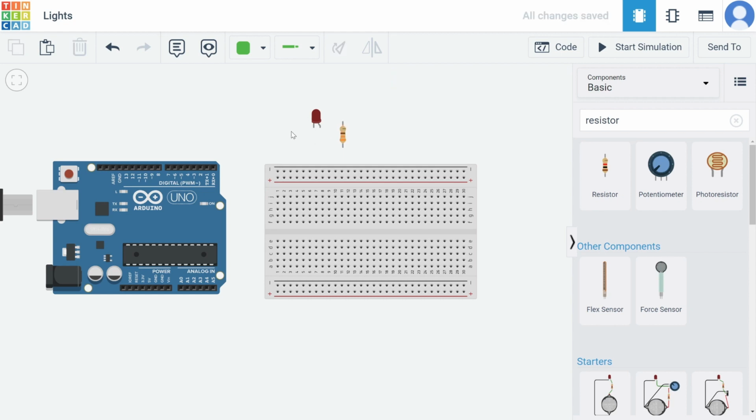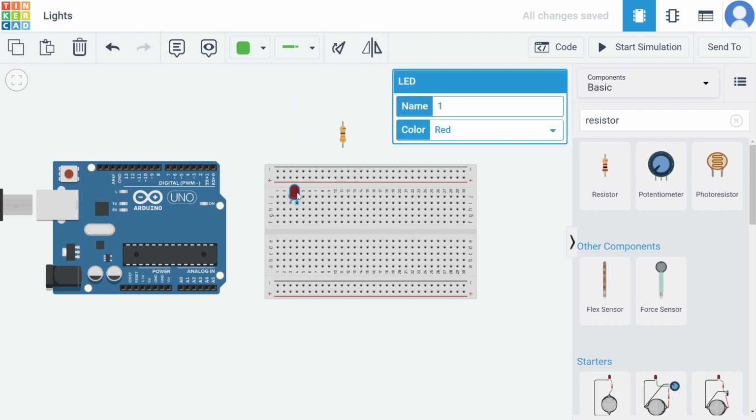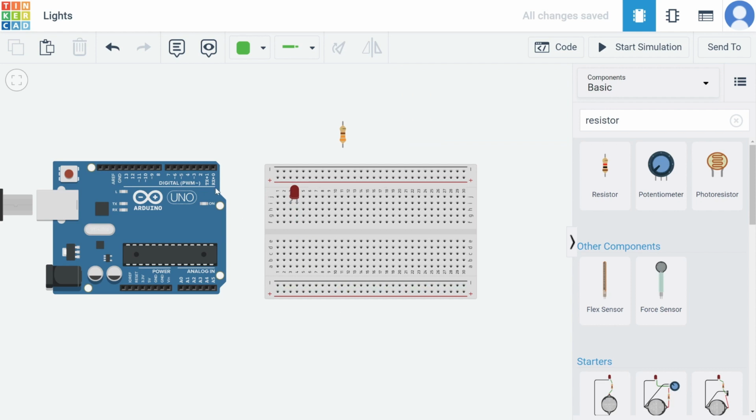And let's just start by talking a little bit about lights. So as you will remember, the positive side is the anode, the longer or the bent one. I'm going to just spin it round so that's on the left here. And if I put it in the breadboard, we'll just start with the 5 volts. I can connect the 5 volts to this here, and I can put it into any one of these other 5 holes, and that will connect, because these are all connected, to the anode here. Okay? This side needs to be connected to ground.